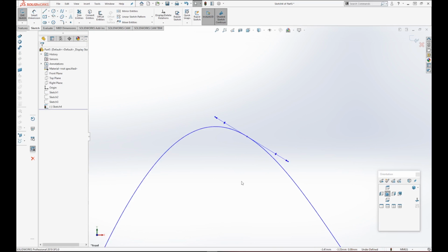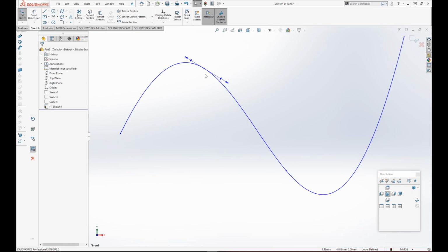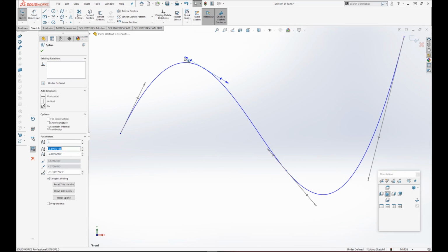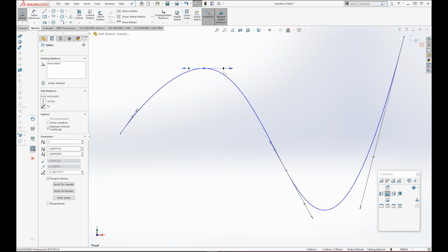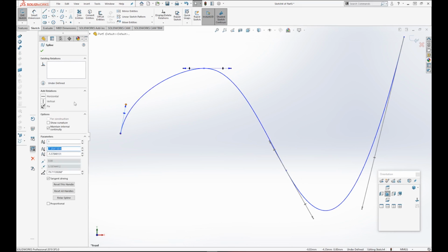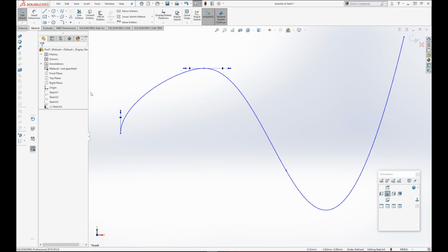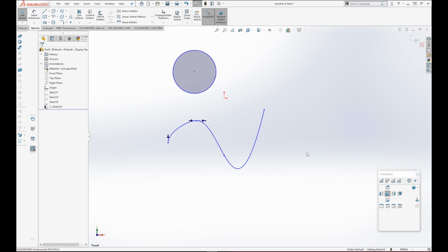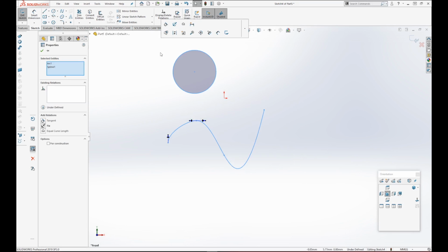So the spline line can get pretty crazy, guys, and you could really mess up. So you got to really be in control. And with these lines too, you could also add relations to them. If I click on the very end vertex right here, you guys can see that I have my relations as well. If I click on the horizontal one, it snaps and becomes perfectly horizontal. I could do the same with that one. Now if I do vertical, it'll snap and be vertical just like that. And I could make sure that all my lines are exactly going in the direction that I want. This is just an initial walkthrough, guys, and it might not make total sense to you right now, but later when we start making stuff, it'll make much more sense.